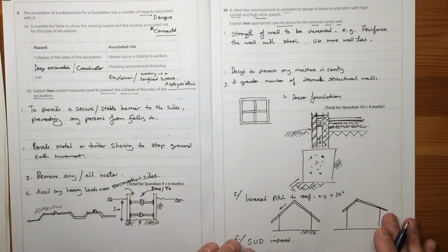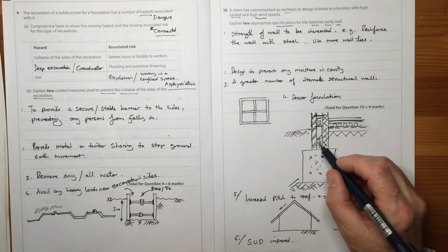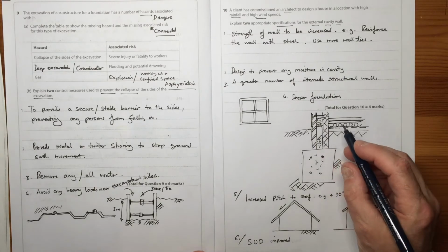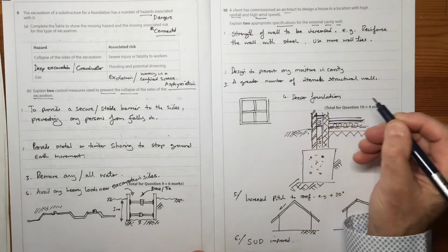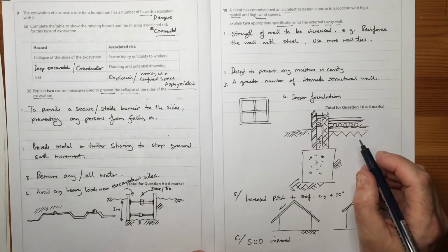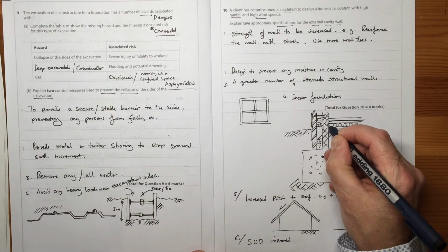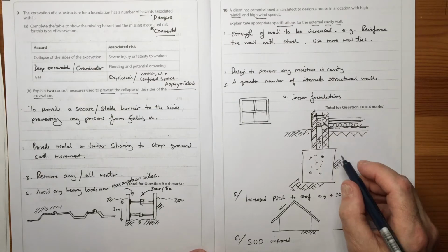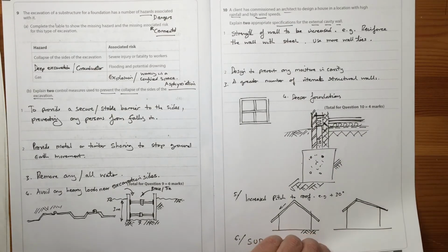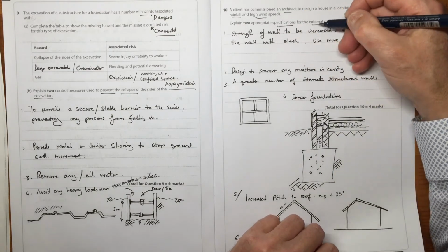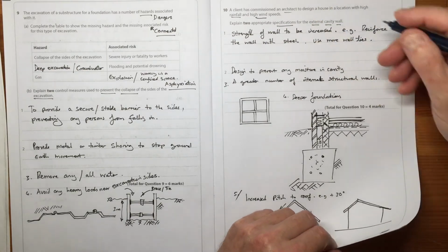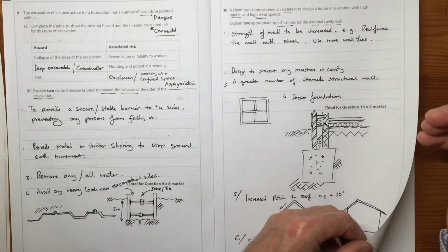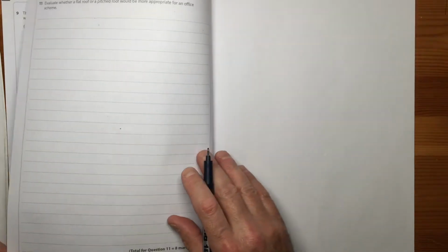Okay, and there's plenty of other things we could do. You could increase the density of the brickwork, so it's a stronger brick bond, and maybe have a mortar which is a little bit stronger in a sense. Okay. All features that you could include in the specifications that the architect may ask for.